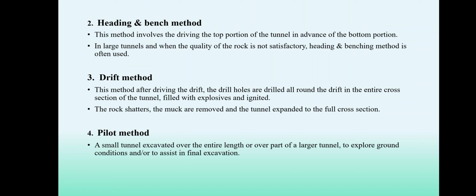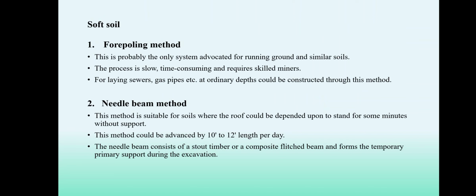Fourth, pilot method. A small tunnel is excavated over the entire length or over part of a large tunnel to explore ground conditions and to assist in final excavation. In soft soil, tunneling methods are preferred.